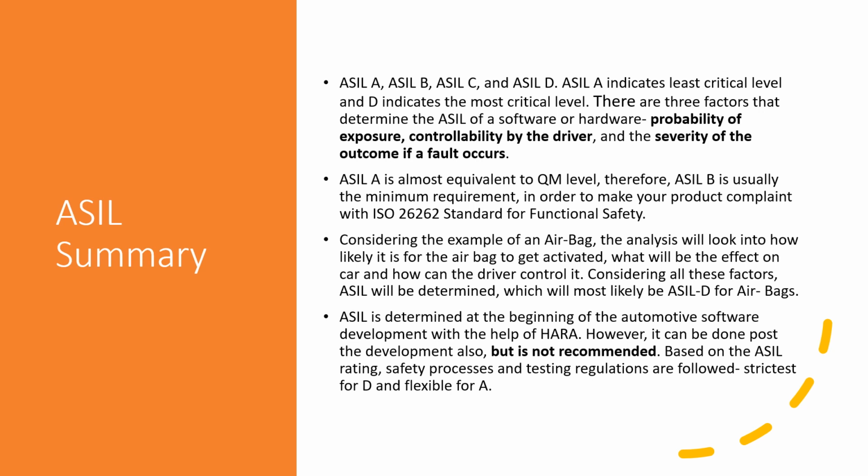Sometimes, in between the product development, the ASIL level is determined, but then you will end up with a lot of rework to adhere to the requirements of that particular ASIL level. So it is always recommended to determine the ASIL level at the beginning of the product.